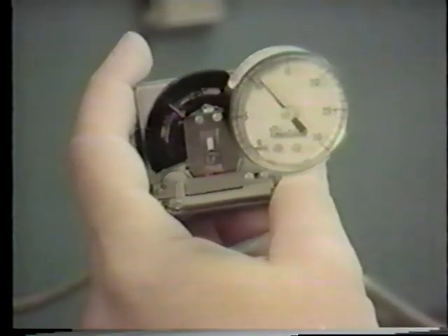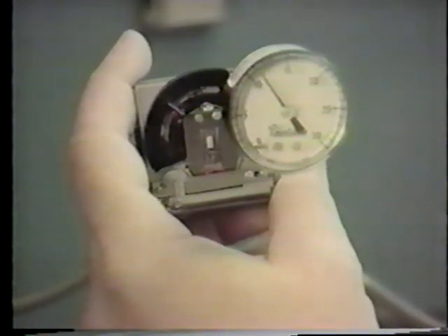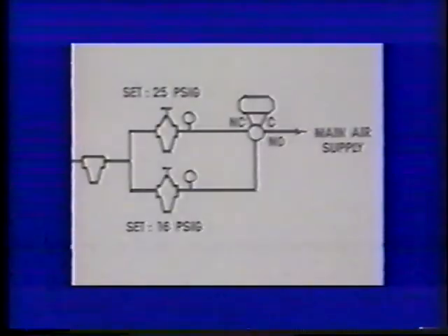As we mentioned earlier, the complete calibration procedure for all day-night thermostat models can be found in the 2214 series datasheet. Now, let's take a look at the summer-winter changeover thermostat. Like the day-night thermostat, the summer-winter model utilizes a dual-pressure main air system. The summer-winter thermostat uses the dual air pressure system for a seasonal changeover of cooling and heating functions.